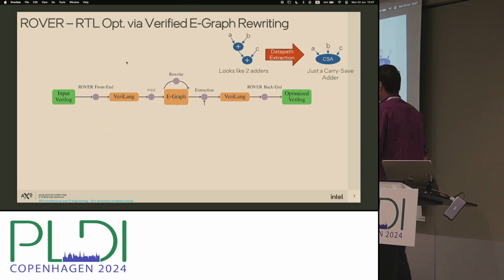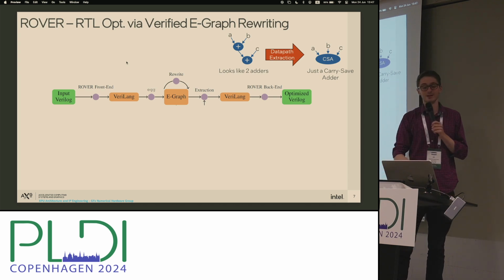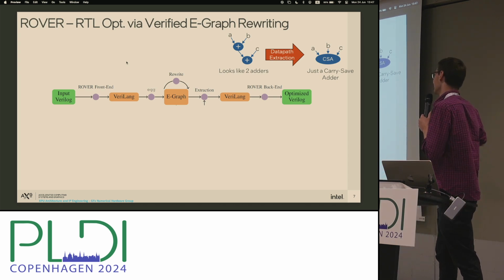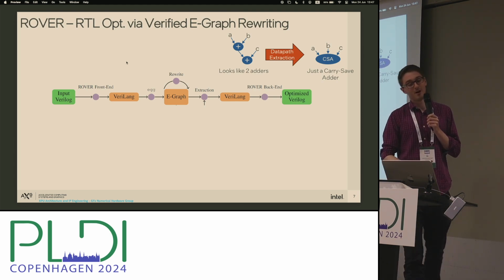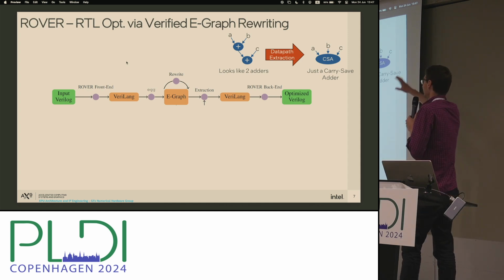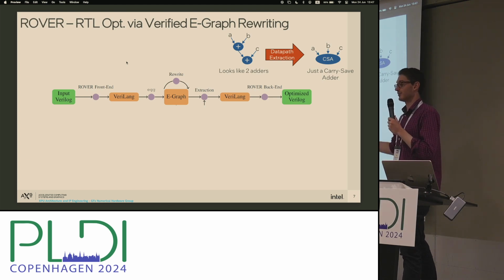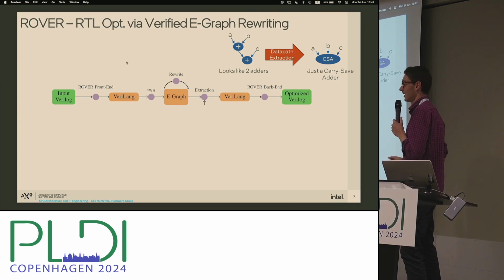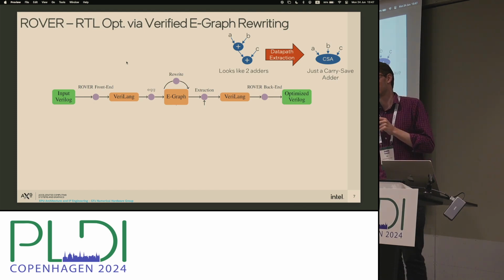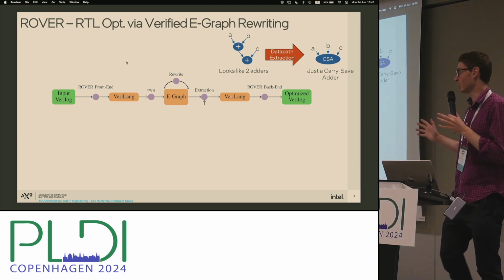And I've presented this tool flow about taking some Verilog in at the front end, doing some eGraph rewriting, applying some area and delay optimizations and extraction to pull out an optimized Verilog expression at the end. What we really looked at in the past is that in the HLS world, you might view 2 pluses as simply 2 adders, right? But in my ASIC design world, a crucial step is that this is not 2 pluses. This is in fact 1 carry save plus that is by far less expensive than 2 separate adders. And these are really important optimizations.